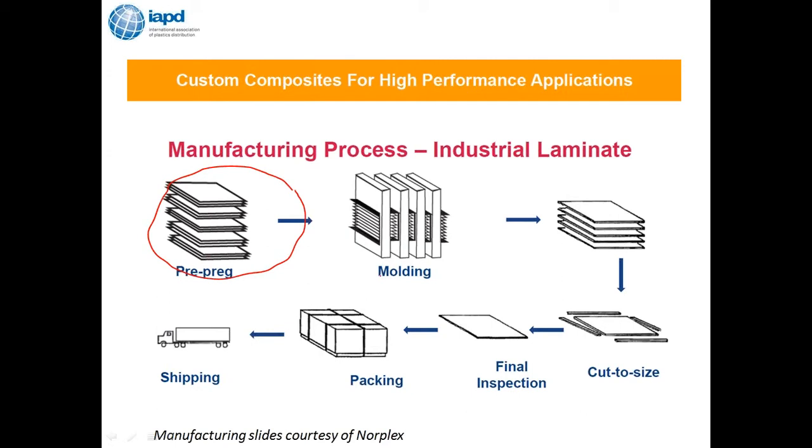The prepreg is the glass cloth, a woven glass cloth. It then goes through a bath of epoxy until the cloth absorbs all the epoxy it possibly can. At that point, it becomes the prepreg. It's allowed to semi-cure, and then you start to make the bologna sandwich.